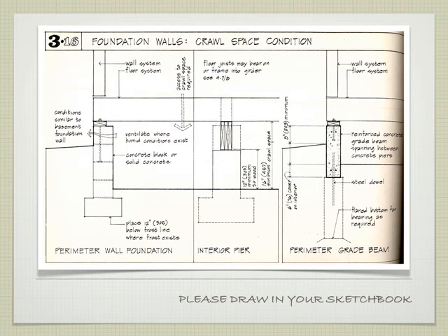So we have our foundation wall that's coming down. We have our footing at the bottom, something like that. On top of the wall, and we'll talk when we get to the wood construction part about the details of this construction, but basically, we have what's called a mud sill there, followed by our floor joist here, which is enough for you to just label floor.